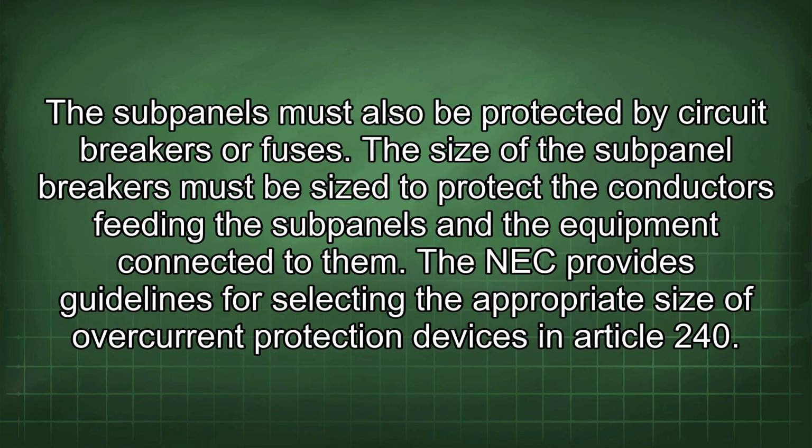The subpanels must also be protected by circuit breakers or fuses. The subpanel breakers must be sized to protect the conductors feeding the subpanels and the equipment connected to them. The NEC provides guidelines for selecting the appropriate size of overcurrent protection devices in Article 240.